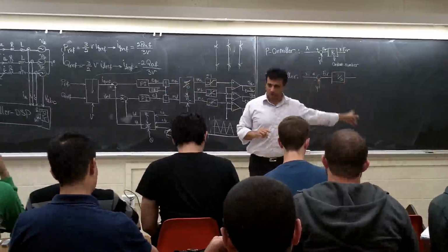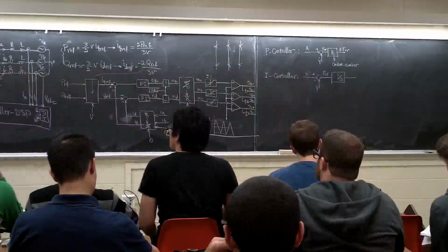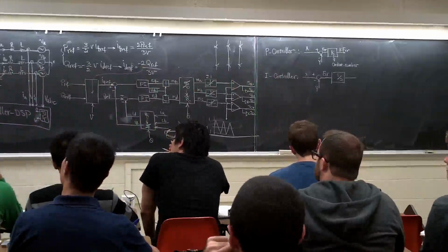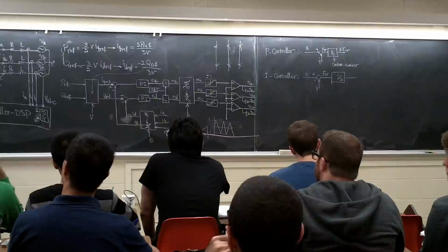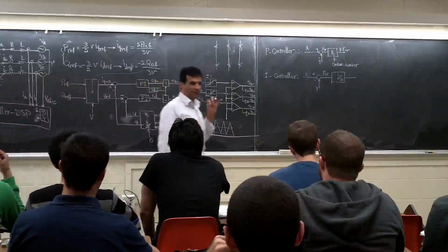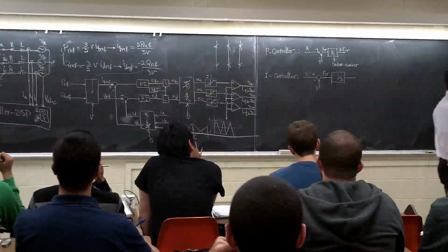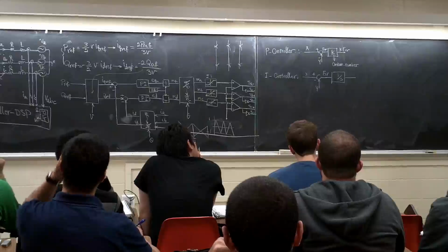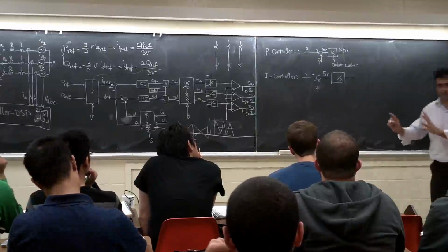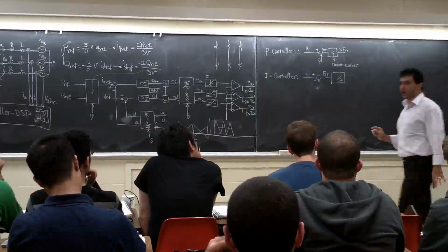The good thing about integrators is that they drive the error to 0. That's the good thing about the integrator controller, because ideally we would like to have a 0 error. Whenever we get there, we are always going to have a small error. But that's fine, if it's small, it's okay. The good thing is that the integrator forces the system to go toward making the error 0. Now, what is the PI controller?